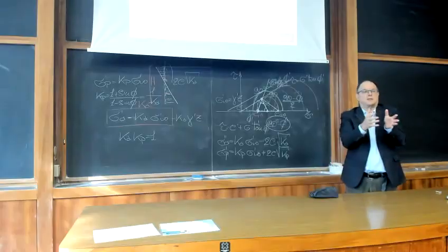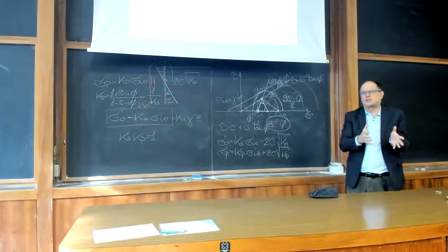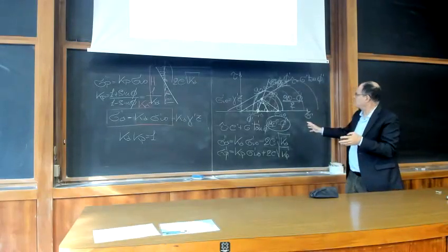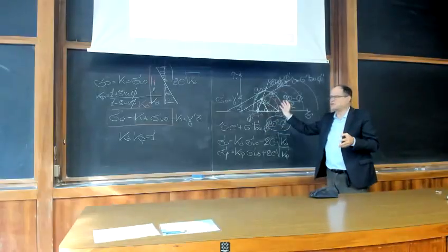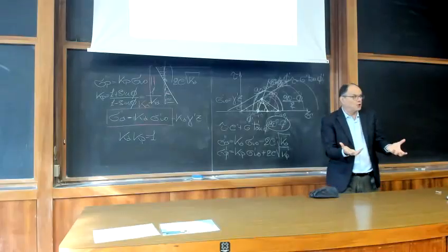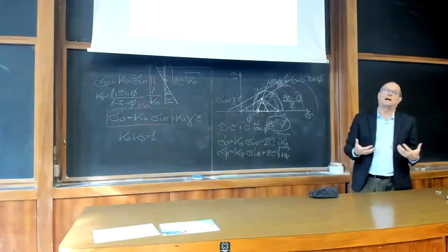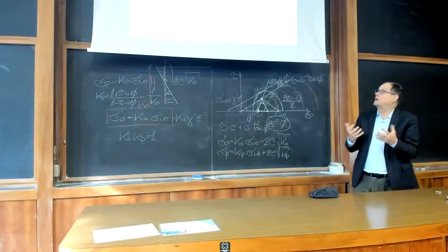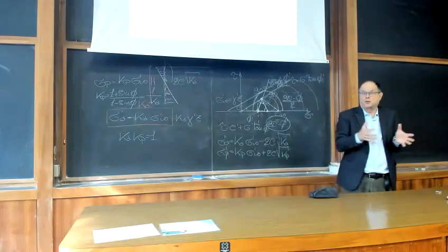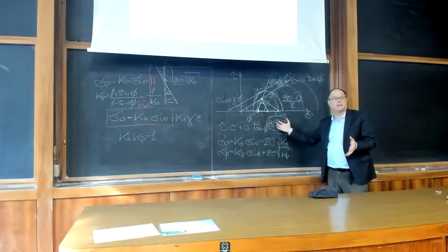Because one thing is the concrete and the stresses that the concrete is able to sustain. Another thing is the soil, which can sustain stresses, tangential stresses. Now we know that typically the strength of the soil is much less than concrete or steel or other construction materials. So that's why you need to enlarge, increase your section, reduce stresses, and allow that these stresses are supported by the soil.